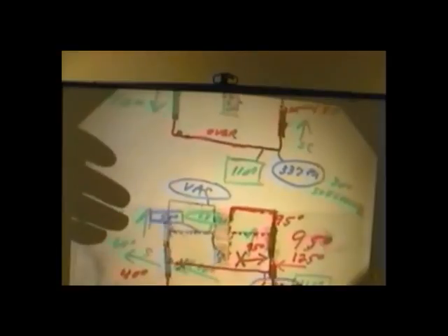like this. It's a very busy transparency copy right now. A lot of stuff in here. But these are the things that you want to teach to somebody. When you teach it 20 times, you get better at it. That's all I can tell you, really. But the chart helps. You don't have to be perfect with it. All you got to do is remember this, and you got to remember that subcooling typically is 12 to 15 degrees for normal. Is this a good chart? Yes. Okay? I think this helps.